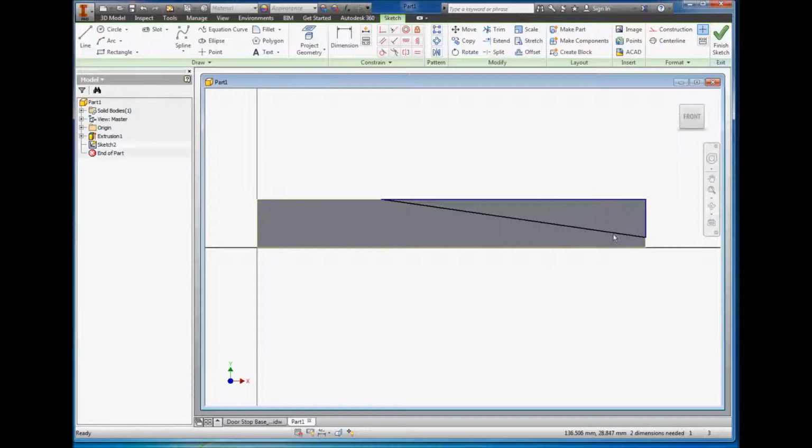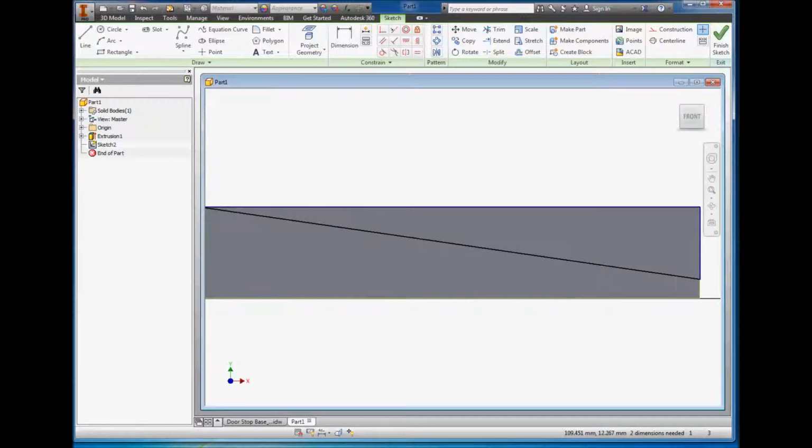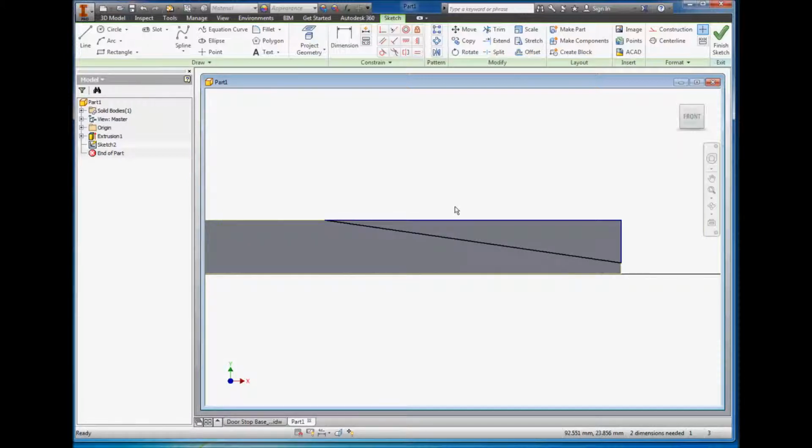Right click, okay. If I zoom in a bit more, I want to turn on my constraint icons to see what I'm doing, to make sure that my squares are yellow. That way I know that the triangle is a closed shape. You can extrude an open shape, but in this case we want to make sure the shape is closed. If I click these yellow squares, I can move these points in because the triangle is not constrained. The only point that is constrained is probably this corner here, because this corner is locked onto the corner from a reference geometry.